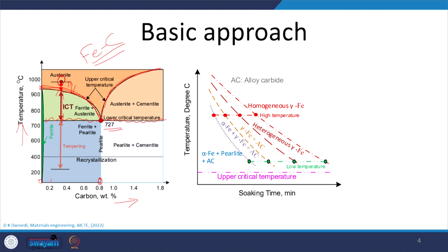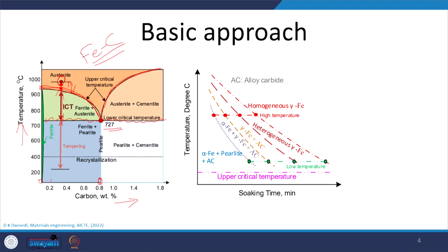Austenite being a metastable phase, subsequently on cooling, depending on the cooling conditions, it forms a variety of phases. So, the desired phase is obtained through controlled cooling in the subsequent stages, but that can be done only if all the soft phases and other constituents have been dissolved and a homogeneous austenitic state has been achieved.